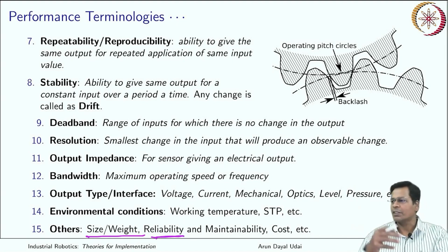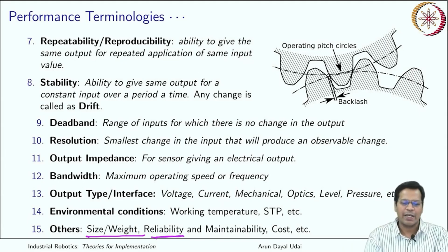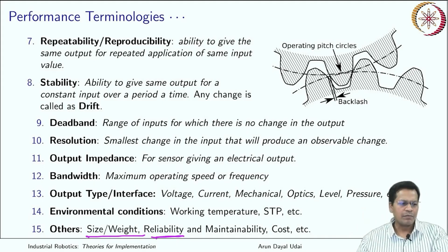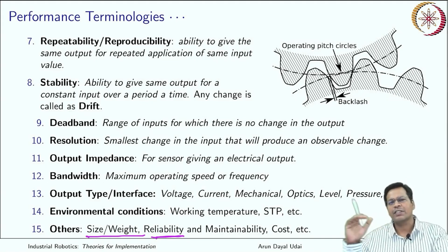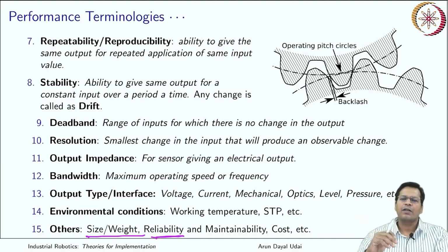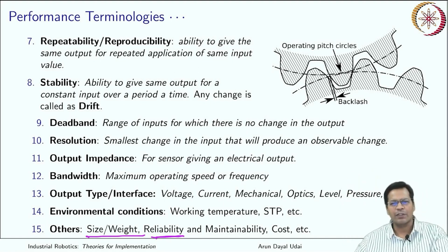It is very much related to many other properties like your system parameters. They do vary with time, or they do vary with the environmental condition. If it goes bad even by a small amount, it goes bad. I'll show you with a force sensor. Even if it is designed to take a load up to 100 Newton, when a robot collides it can go up to maybe 1000 Newton.